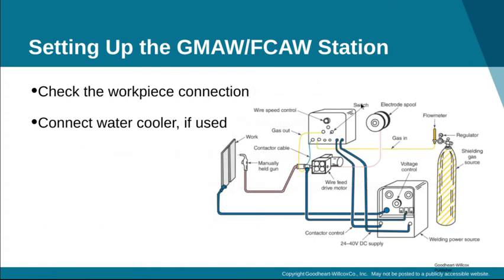So, going off of my Ivy Tech kids that I've been having in here, the ground clamp is the first thing that you should check. I was actually getting a little bit peeved at some of my Ivy Tech students. It'd be like week 7 or 8, and they'd say, "Hey, Mr. Chris, the welder's not working. It won't strike an arc." And I'd walk in and there's no ground clamp on the table. It should be the first thing you check if there's an issue, especially if it's not striking an arc.